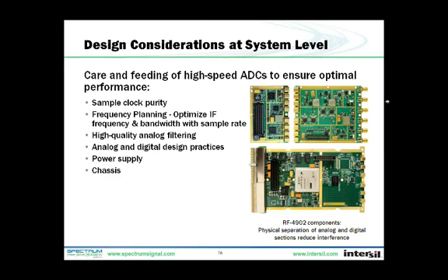First, the ADC sample clock and clock distribution chain must be very clean, and clean in several ways. The clock needs to have low jitter, also measured as phase noise, and as Mark mentioned, the jitter requirement gets tighter as the input frequency and hence the slew rate increases. It's part of the price you pay for wide bandwidth. Clock spurs will also show up in the digitized signal from the ADC and may interfere with desired signals. You saw one slide that Mark had on that. You want your clock and your frequency reference to be very clean and free from spurs and noise.